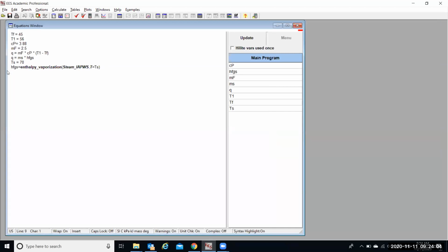For example, that you need to calculate enthalpy for the air, which is leaving the humidifier at a temperature of, say, 39 degrees centigrade and relative humidity of 90%. Then temperature T-air2 is going to be 39. And relative humidity, let me call it phi, is equal, this is the relative humidity of air, and phi is 90%, which is 0.9.